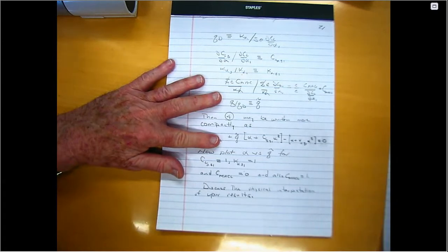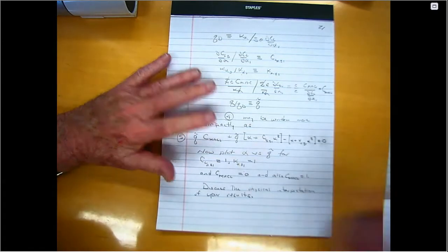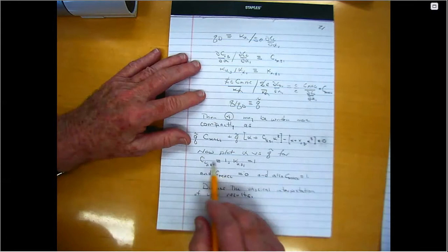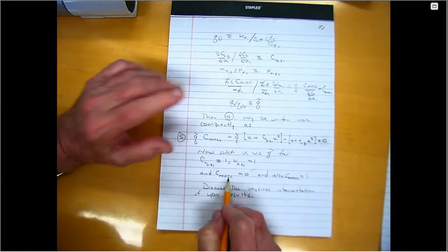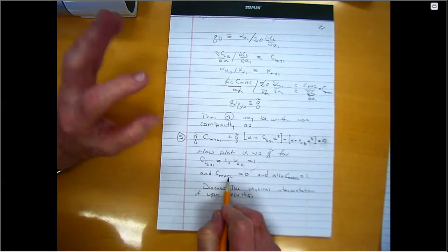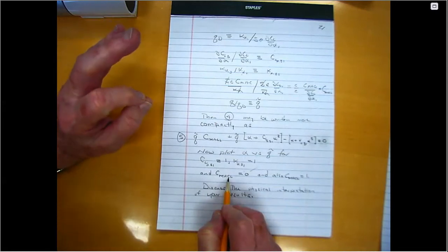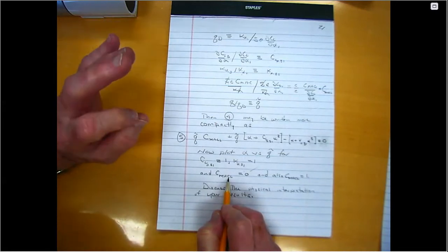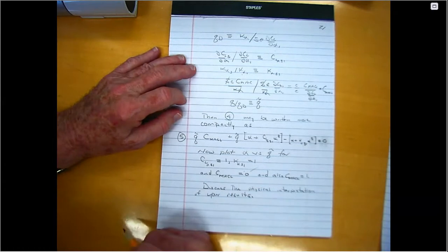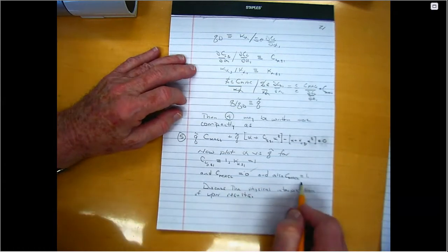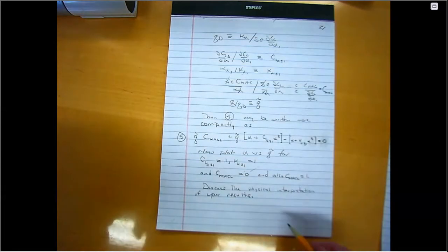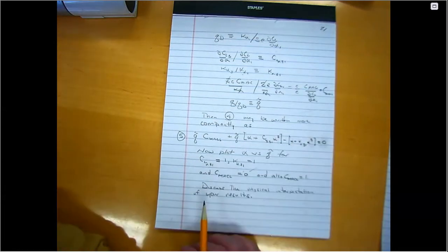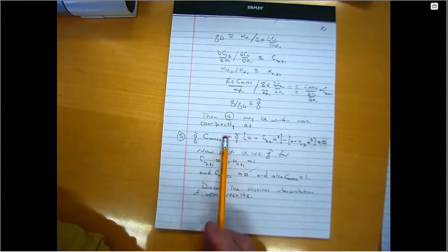One of them is alpha equals 0. But if I eliminate that, there's still 2 more solutions. And so I'd like you to plot that for both cases where I set this coefficient. Remember, this is the non-dimensional aerodynamic moment about the MAC. And typically, it is a pretty small number. And often in divergence analysis, people just collect it all together. But I'd like you to also plot it for the value of 1, because it will give you some additional insight. So you can do that, and then tell me what it means physically, to the best of your knowledge and experience.